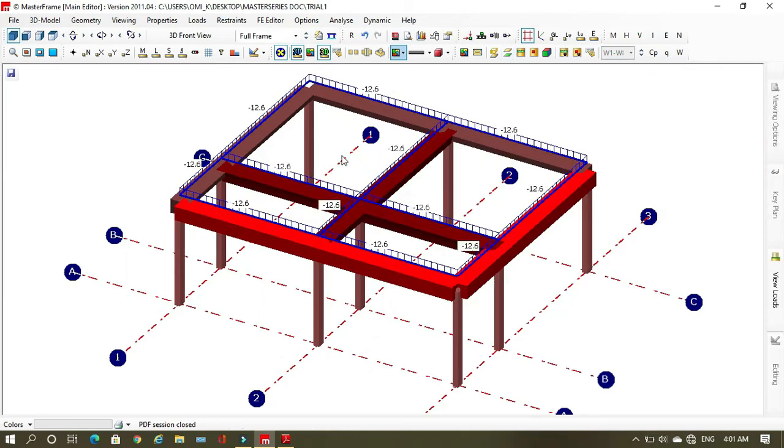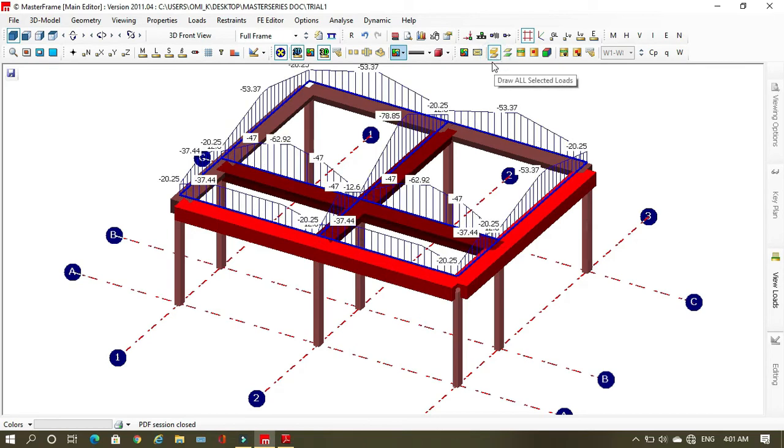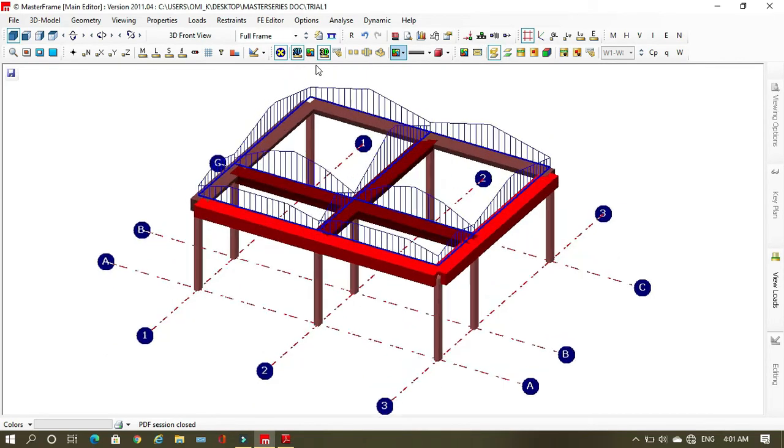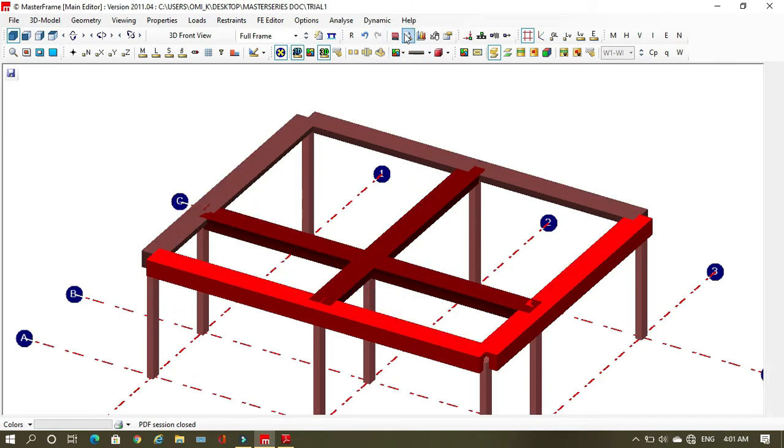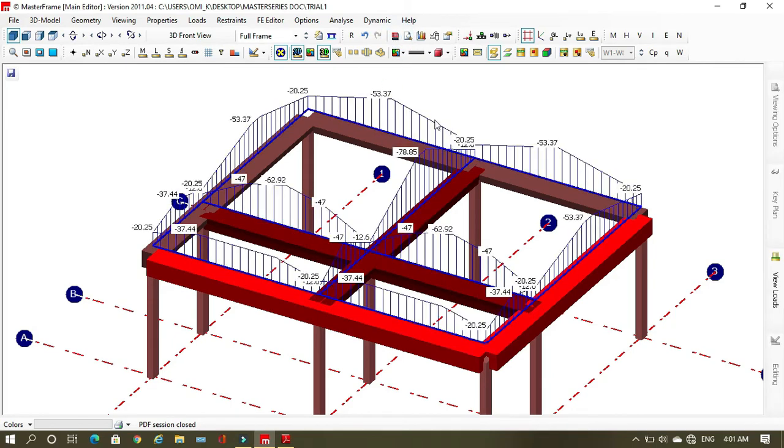And if you want to check your slabs here, if you click this one, it shows now. You see now these are our loads from our slabs and wall, and mind you, these are moments. These are not loads, these are moments. It's already calculated the moments. Okay, but these are moments without analysis. It has not analyzed anything. It's just calculated it.